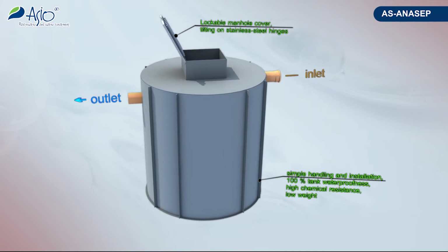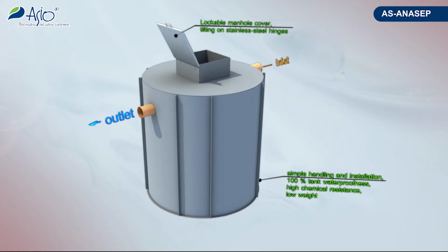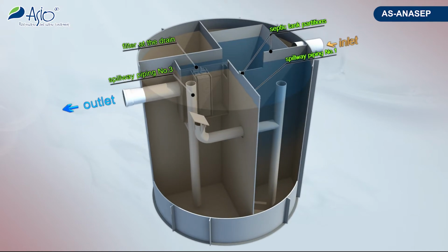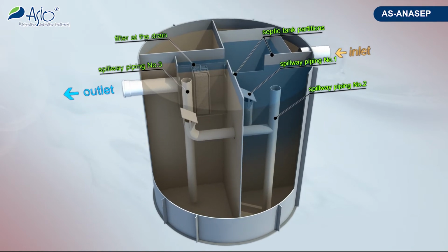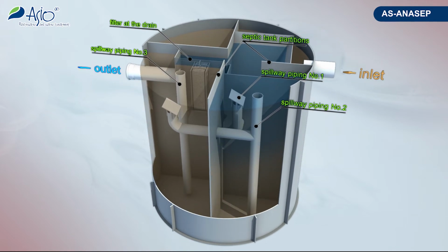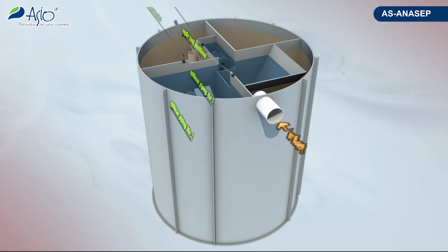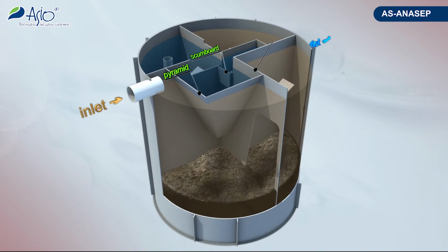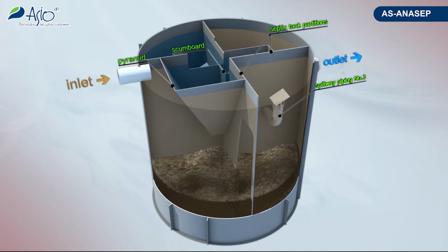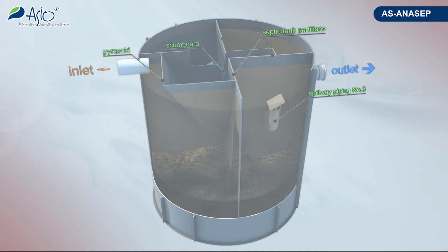This septic tank can divide the flows in a manner that its hold-up or retention time is increased even threefold in comparison with conventional three-chamber septic tanks. Naturally, this leads to an increase in efficiency, as well as in a decreased production of sludge. Consequently, the sludge production can be further reduced by the use of various biopreparations.